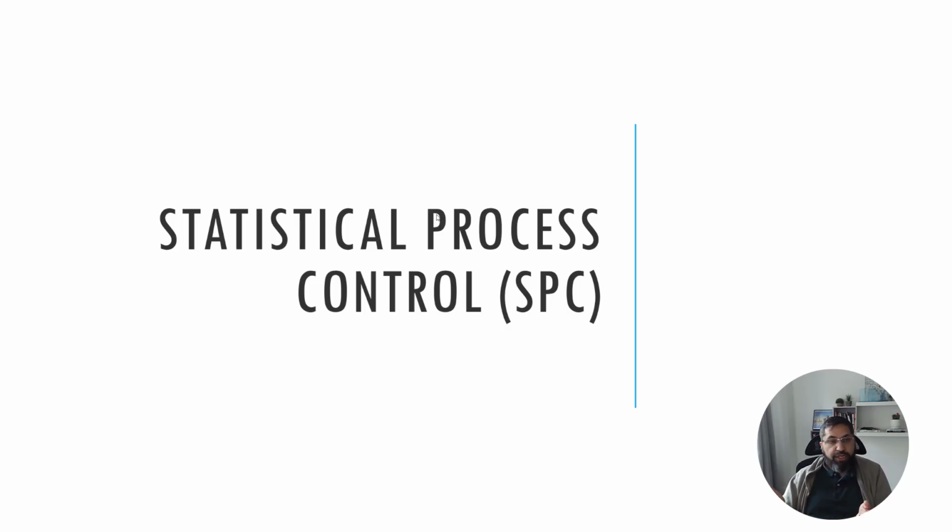There's no point in trying to control an incapable process, because an incapable process is going to generate defective output by definition if the process is not capable of generating the right output. So first you have to get the process capable, at least at the Cp level, which assumes a centered process. Then statistical process control will detect off-centering, and at least at the Cp level you have to be capable, even if Cpk is a little bit off because you're off-center, and then process control will detect when it's off-center and help you bring it back. And so you have to have a capable process before you go into statistical process control, which is how it should be taught.